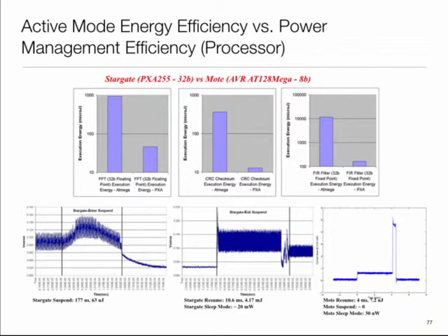So what you have out here are two embedded systems. One is a high-end running a 32-bit type processor, and the other is an 8-bit type thing. These are somewhat old, roughly 10-year-old devices. So first thing to bring out is that this second device, by any stretch, is a lower power device. This is milliwatts. This is watts. Almost more than 2 orders of magnitude difference between the two if you were to just look at the power numbers. But when you look at them in a realistic application setting, things look very different.